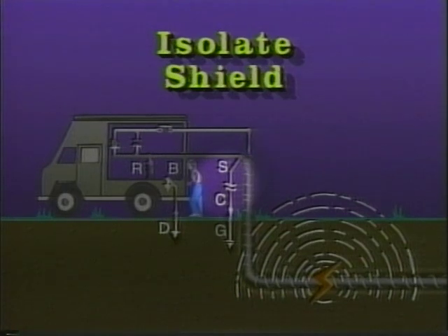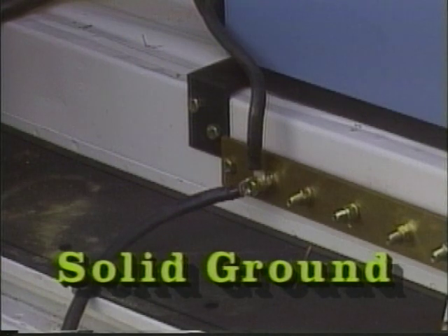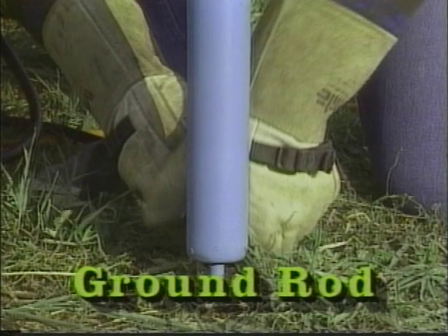If the thumper is being operated from a vehicle, a solid ground, B, must be applied between the vehicle and the thumper housing with a short number 2 or larger conductor to ensure the vehicle does not float or seek its own potential. This is also true for the earth ground of the vehicle. A driven ground rod, D, should be placed as close as possible to the vehicle to make sure the earth in the surrounding area does not float.